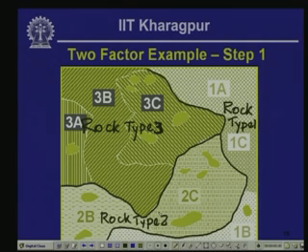Then on this map we have to superpose the areas where we observe historical landslide activity, and these areas could be in the form of areas where landslide scarps are visible, and areas which are underlain by landslide deposits, such as deposits that get generated because of landslides, such as debris flow and slope failure deposits basically, and those are indicated by these solid shaded areas.